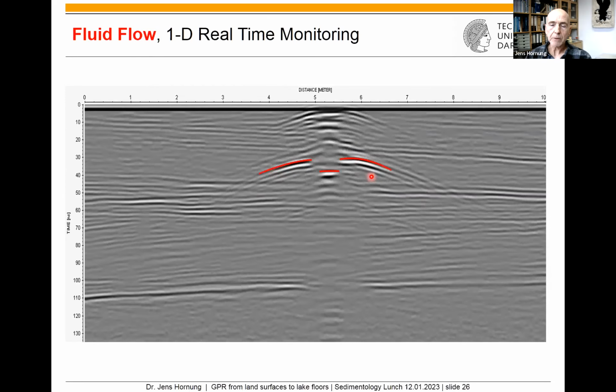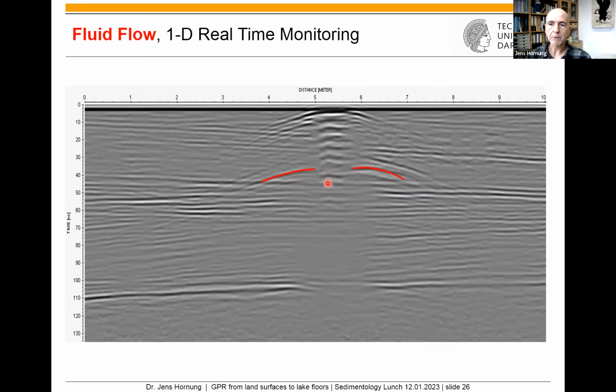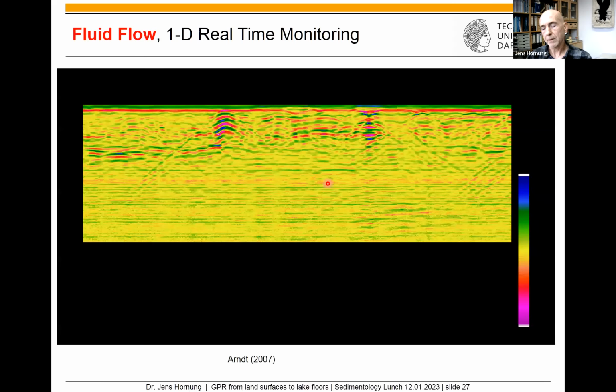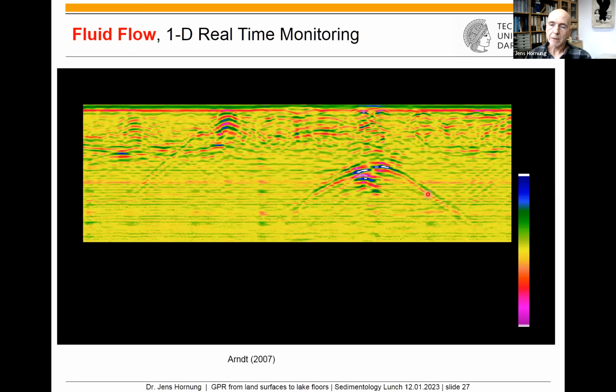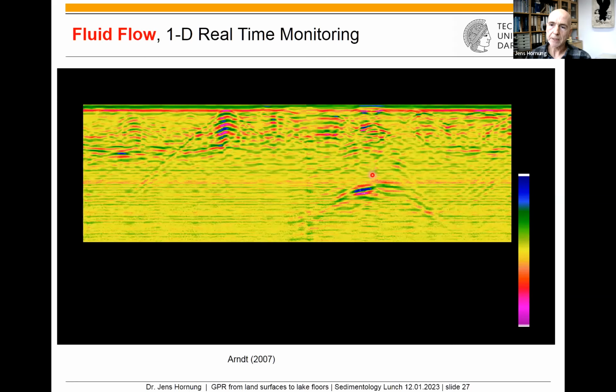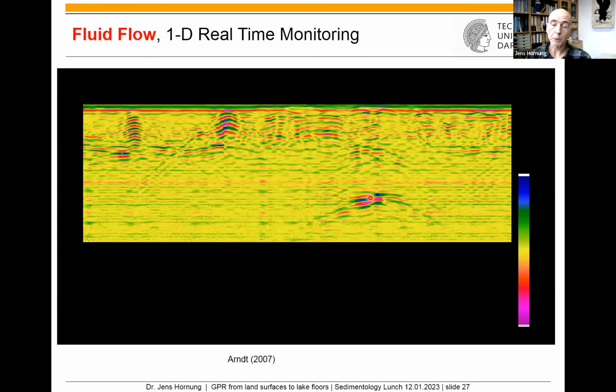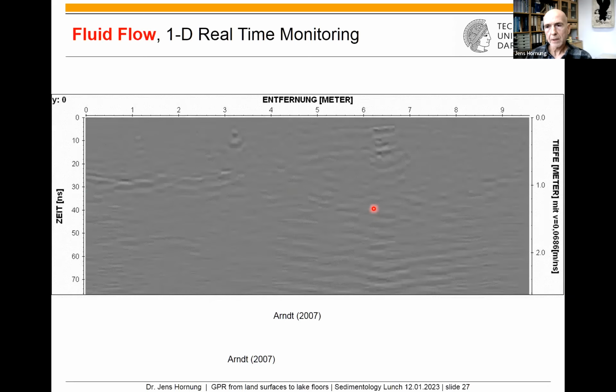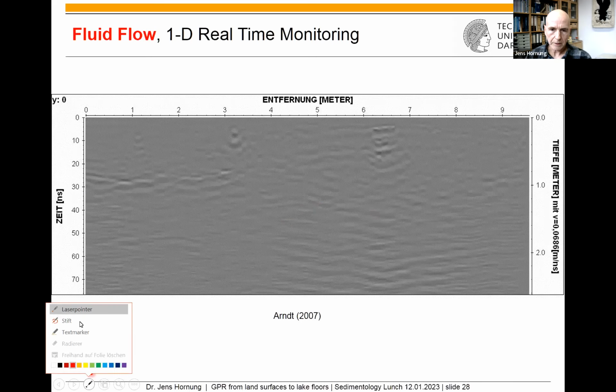From this data, you can calculate infiltration rates, infiltration velocity, K values, whatever. This is another example. I let it run in color, that the water infiltrated here and then it went down. This is, in this case, a water pulse only for 5 minutes, and the waterfront goes down into the subsurface. This is another example, and I need to start it.